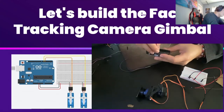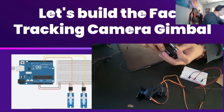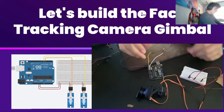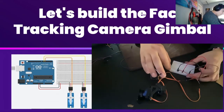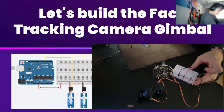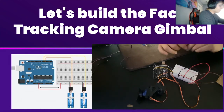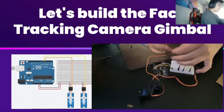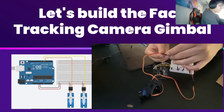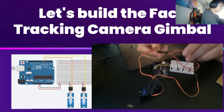If you have an Arduino, you'll be able to see the lettering on the side and on the front, so that you know where you're connecting it to. So now let's go ahead and connect the 5 volts to the positive, and then the ground to the negative. The only other thing we would have left to do is to connect the PWM pins that we send data and values to, so the servo knows where to turn.